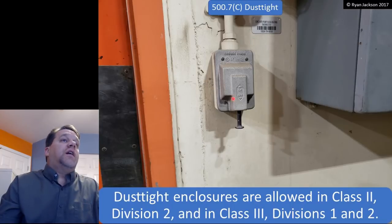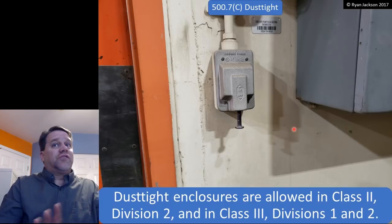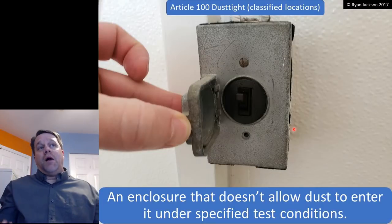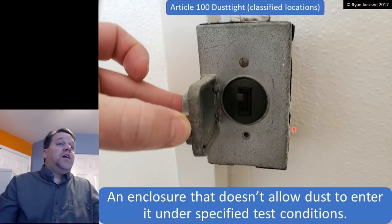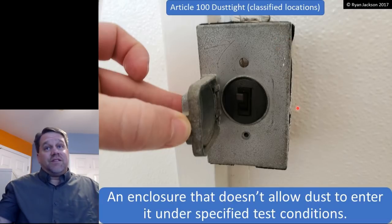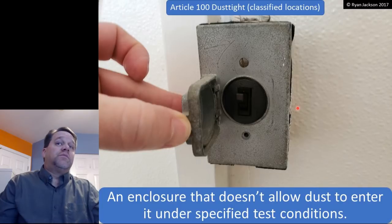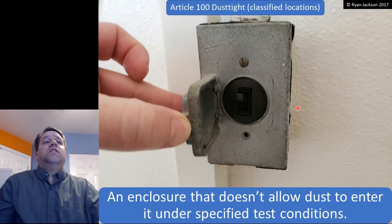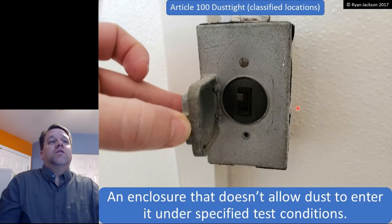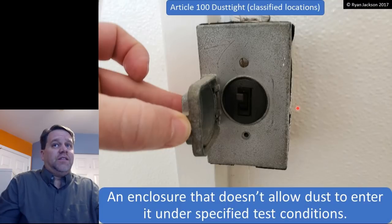Now this is a dust tight enclosure, but that's a very extravagant version of dust tight. This is also dust tight, a regular outdoor box with a gasket. All that dust tight means is it's an enclosure that doesn't allow dust to enter it under specified test conditions. If you have an outdoor box and you got a gasket, is that dust tight? Yeah. Is that dust ignition proof? No, not by any means. But it might not need to be, right? If I'm in a Class 3 Division 2 location, Class 2 Division 2 location, I only need dust tight, not necessarily dust ignition proof. So dust tight is actually pretty simple.